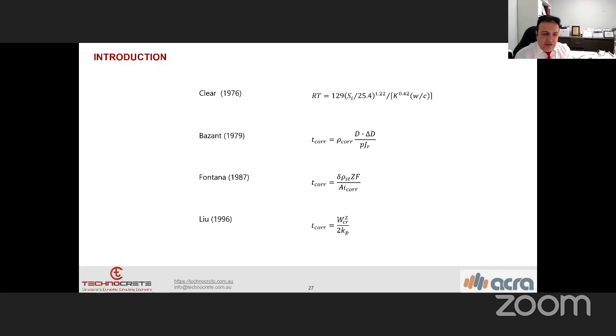And the cost, I think it depends. We have to consider different factors in order to decide a proper strengthening. Sometimes we cannot use wrapping because of the ratio which we have. The carbon fiber wrap or laminate can provide up to a certain strength for the structure, and if that ratio is more than the carbon fiber strengthening can provide, then we have to use other, conventional or steel, strengthening.